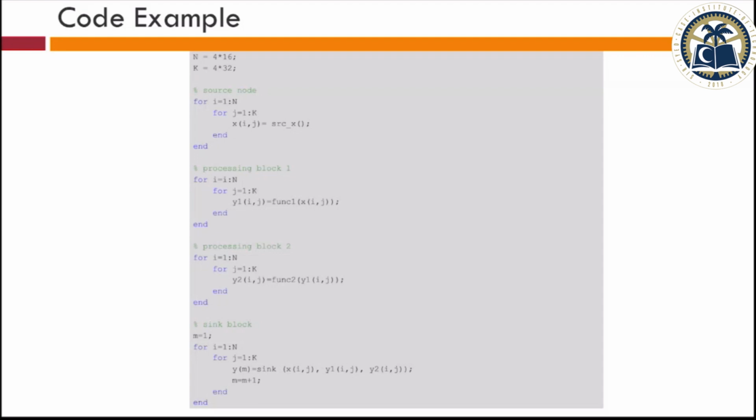You have to worry about that. Even when you are generating Python code, we would prefer that you generate it in the same manner. If you intend to develop an architecture, try to generate the Python simulator in precisely the same architecture that you have for the hardware. That is very important. Unless you do this, you will not be able to do white box testing, or exactly reuse the code you generated for the software implementation in the hardware implementation.